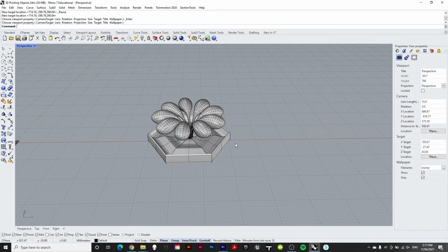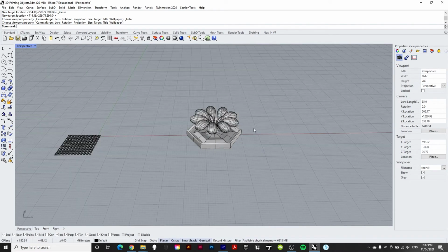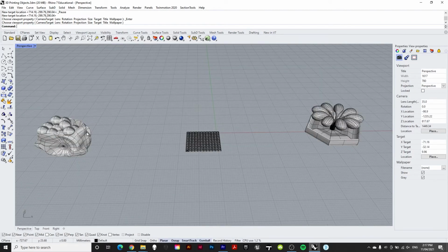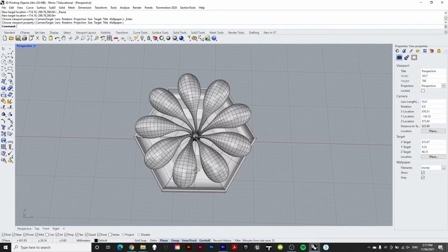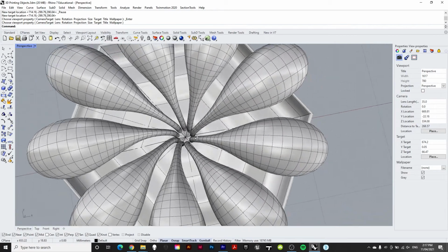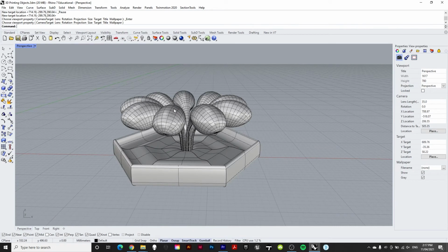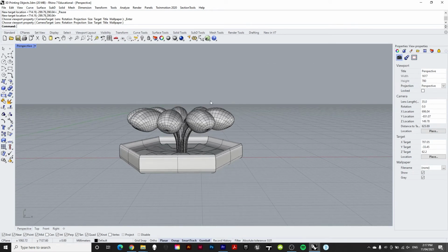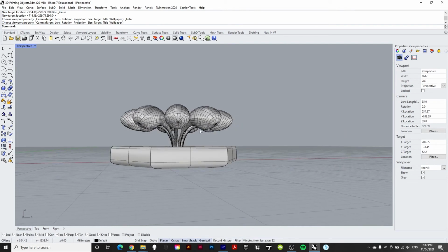Now, when we have a geometry like this, which is made up of multiple parts, it's not as conducive to 3D printing as something like this, where we can turn all of our geometries into one geometry by just booleaning them all together. These geometries don't actually touch each other. They have a gap between each one, and so it's going to make it really difficult. Of course, we can Boolean this down to its base, and then we can 3D print the whole thing like this. However, the gap between here and here is monstrous.